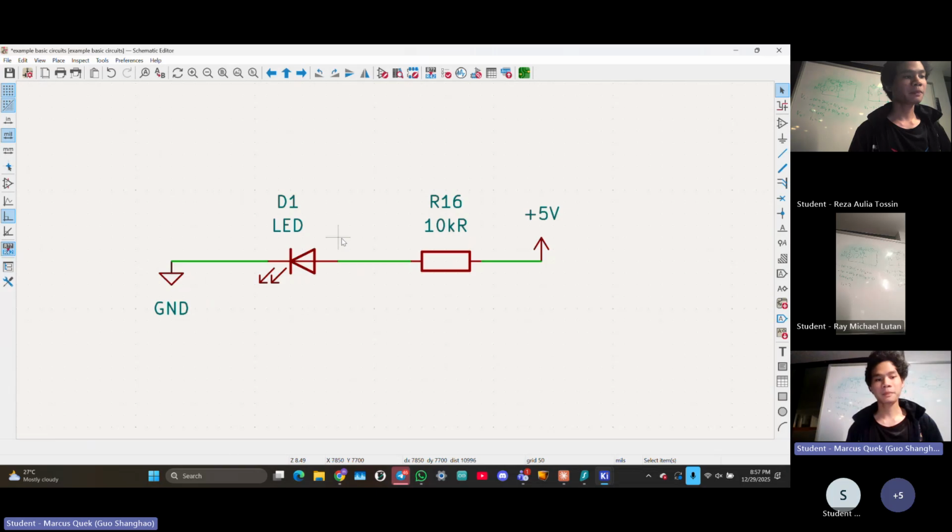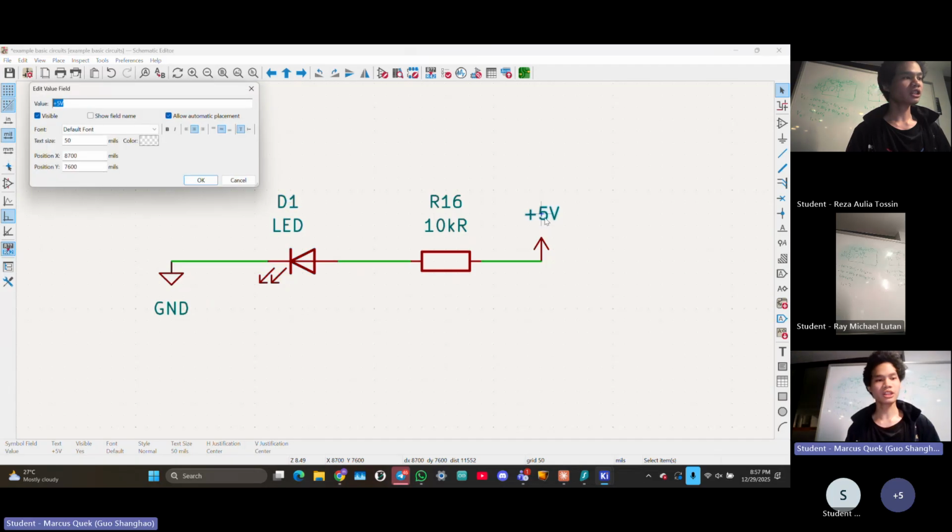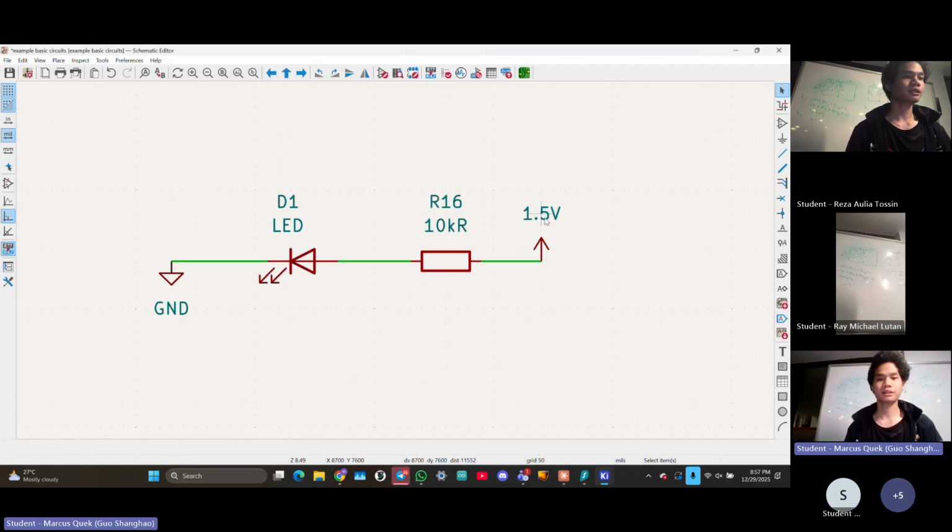All right, so we need this because the LED has a maximum voltage across it. Actually, 1.5 volts is quite safe, but LEDs usually can have up to like 3 volts across them. So if I change this resistance, then I will have a different voltage across the LED, which will make it heat up more or less depending on whether I increase or decrease the voltage.